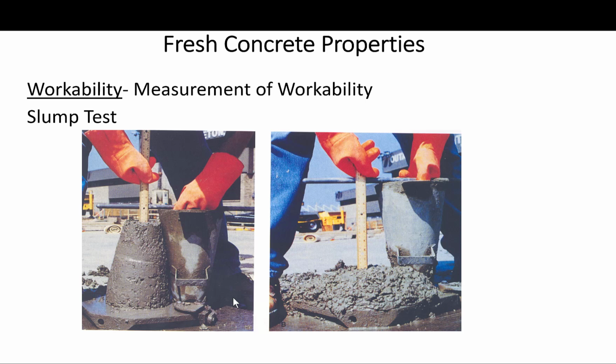So also, these tests are single point tests, and therefore cannot be expected to describe the properties of a material such as concrete. You take the slump test, for example, at the point of discharge from the transit mixer to the pump, or maybe sometimes at the other end after it's been pumped to the location where it's being placed.